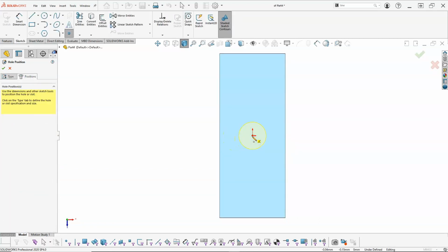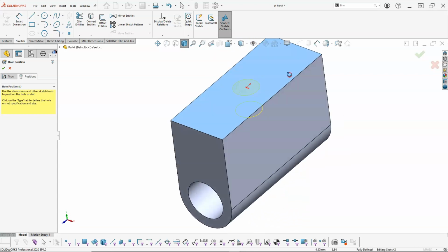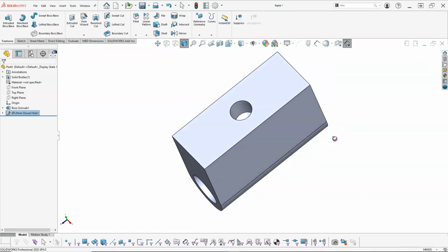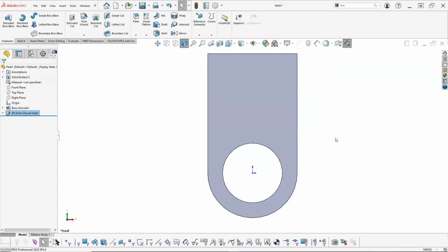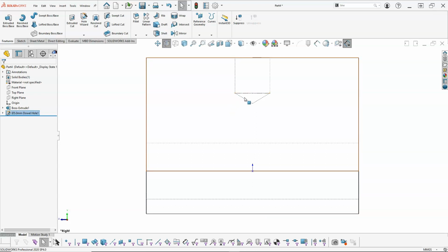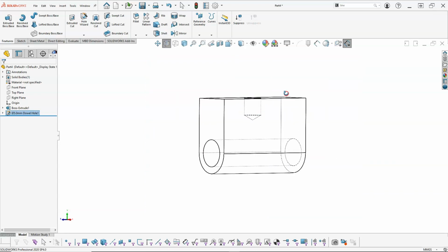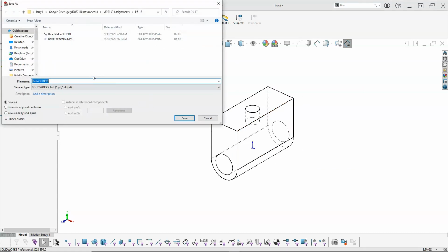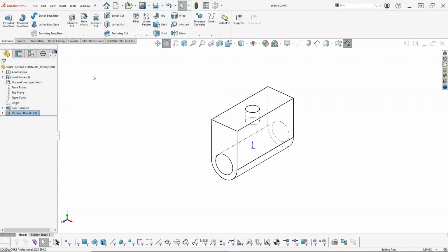All right, so if I bring this back over, I can position it at the origin, which centers it on the part, and places our dowel pin hole. Alright, so if I go to the side view, we'll see the drill point. That looks pretty good on the proportions, so the next thing is to save it. And call this the slider. And that one is ready for the assembly.